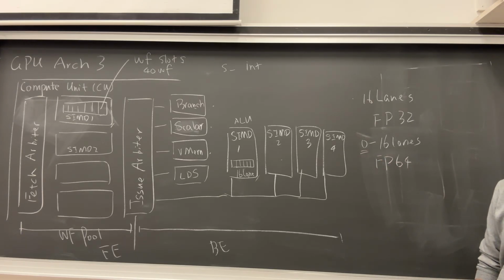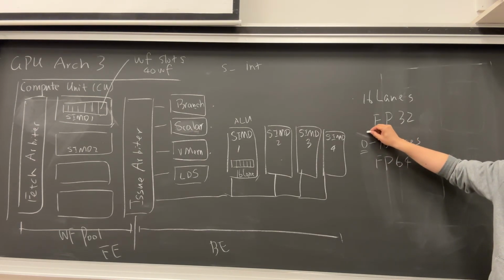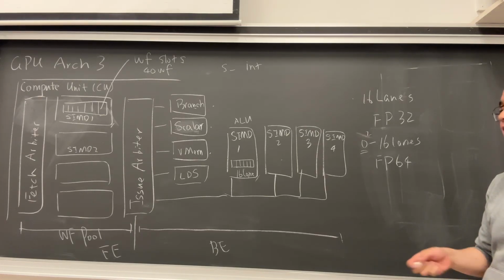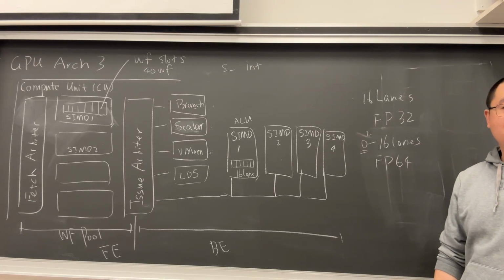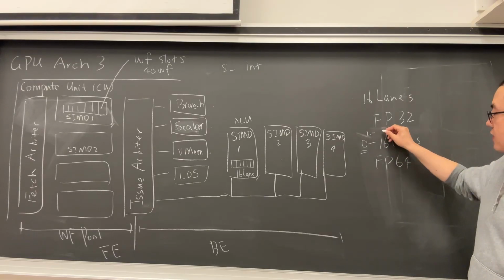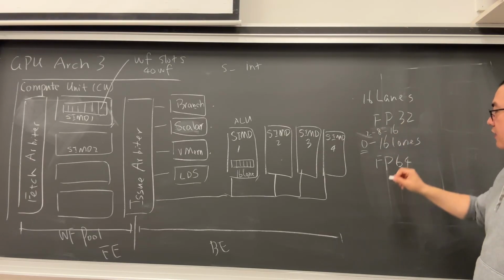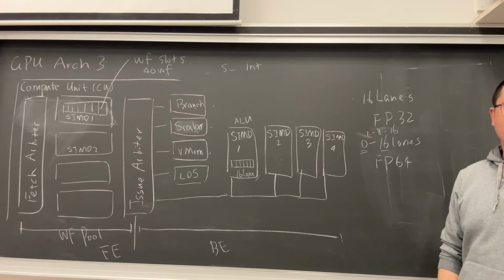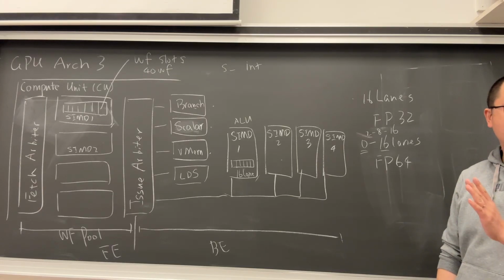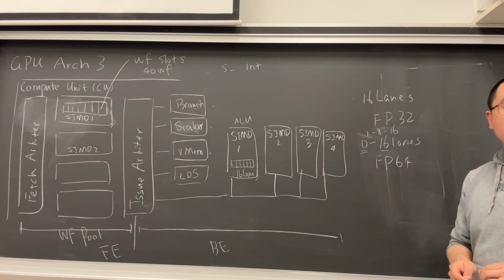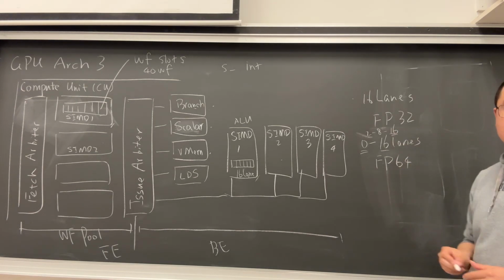They don't care about double precision operation. Then a rather standard configuration is maybe 2 of them for a regular gaming GPU. They reserve some capability of performing double precision operation, but not much. We can barely do it, but don't expect too high performance. Then some others may have 8 or 16. What has 16? For example, high performance computing, MI300. I don't really know what exactly the number in MI300 is, but those super high-end professional compute-oriented GPUs tend to have 16 lanes.